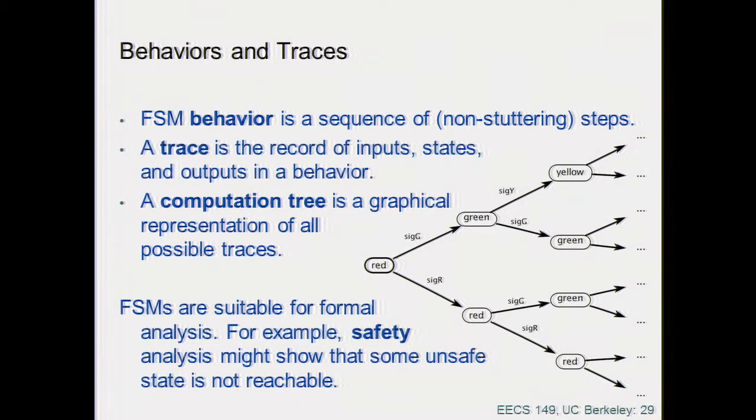You nose down, right? You go nose down because you increase the speed, you get the lift, and then you go up again, right? But you had the turkey pilot, and the turkey pilot saw the plane doing like this, we are crashing, and was taking it up, right? And the more the plane wanted to go down because it was losing speed, the more the guy was taking it up, and the more speed it lost until, boom, stall, catapult, right? So the controller was preventing you to go to the stall, right? And so the controller was changing the state of the system to avoid going into that state, right? So that's what controllers do.